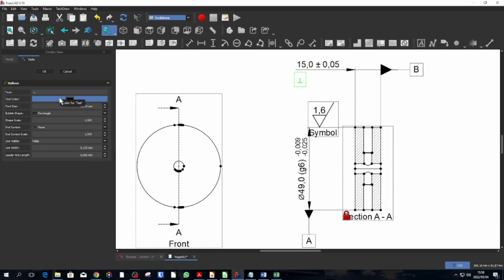So what we do is we press Shift and backslash. On my keyboard that is a straight line, as you can see. It enters the separator, and now we need to add the value 0,05 and Shift backslash again, and this will be relative to datum A.